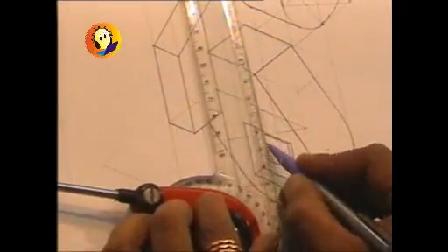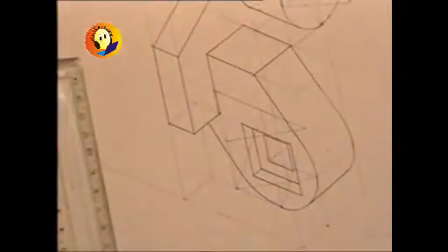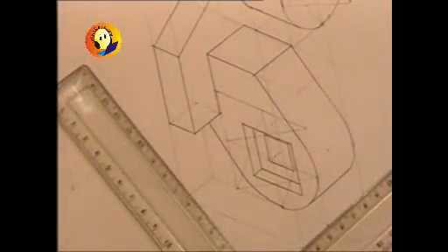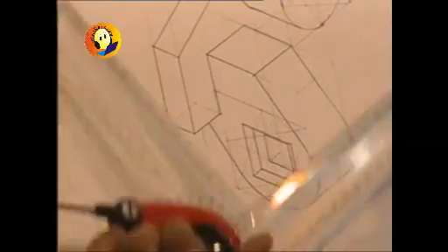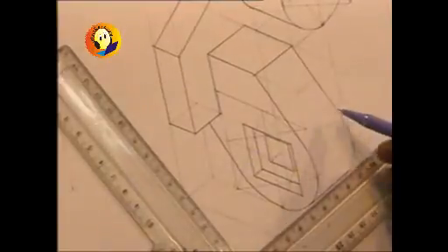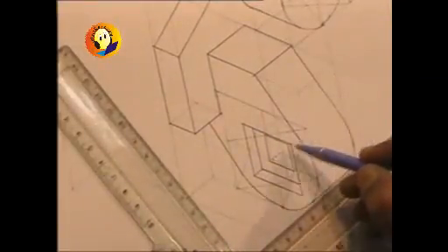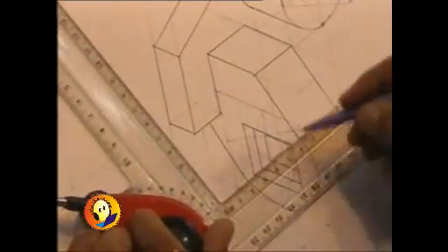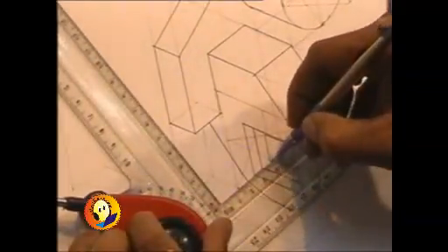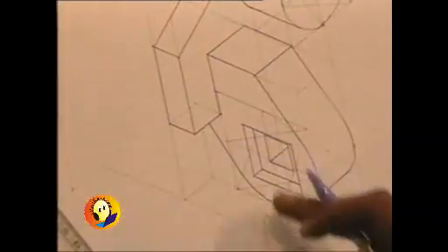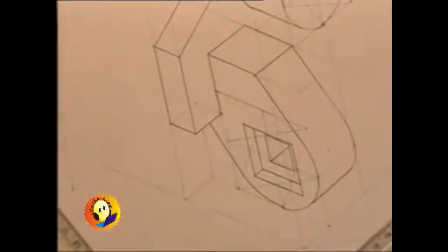So this has been darkened, the square, and then you are required to check whether between these two diagonals we have a distance of 24, because the total width was 30, 6 is lost here, so this hole will have a length of 24, but we don't have 24 distance, so that we can draw this line just fully and leave it. This is how the square hole will be drawn.